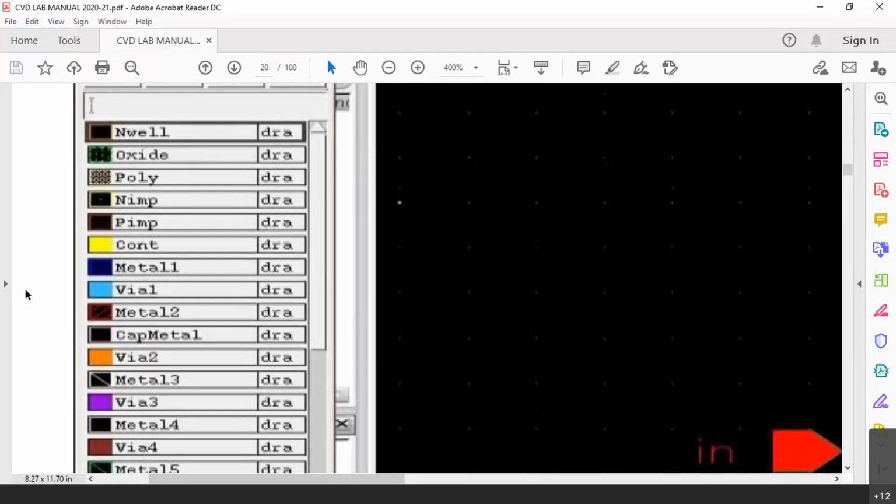That polysilicon is the gate material contact, below which there will always be that gate oxide, without which the transistor will not function at all as a field effect transistor. So the point here is, we don't need an oxide mask separately. Once we make a polysilicon mask, that itself is going to work as an oxide mask.